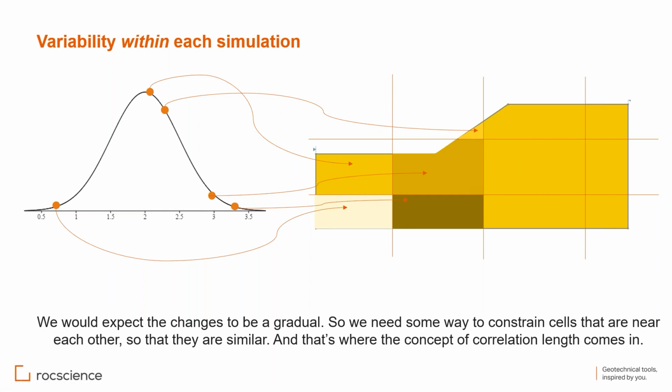Or is there a rule or a parameter? This is where we talk about the concept of a spatial correlation length, which is defined as the length over which the soil properties are the same. In other words, if you have two boreholes taken from adjacent locations in the soil profile, they tend to have very similar values. And the range over which they have similar values, we call the spatial correlation.